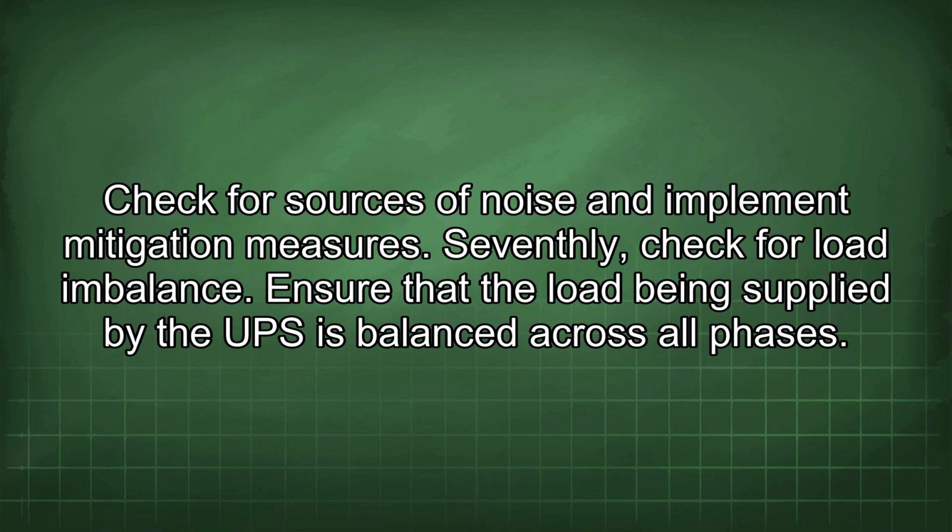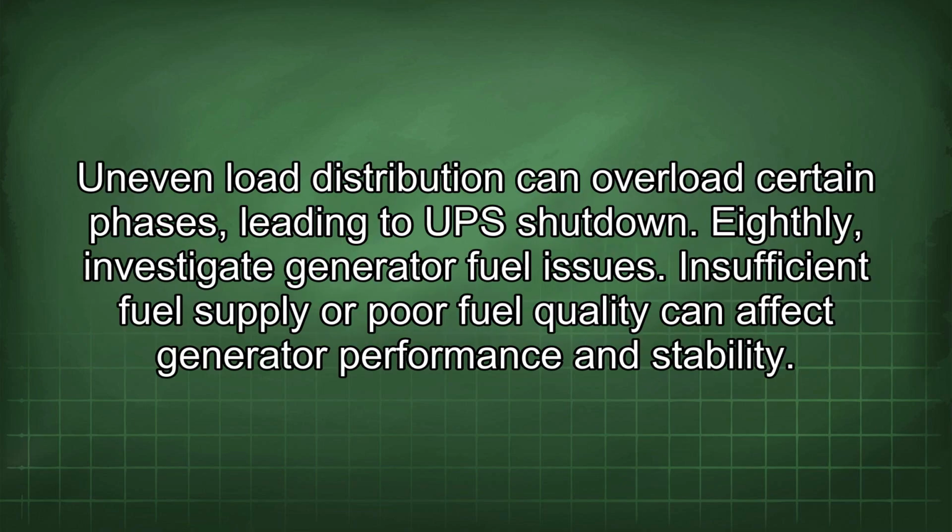Seventhly, check for load imbalance. Ensure that the load being supplied by the UPS is balanced across all phases. An uneven load distribution can overload certain phases, leading to UPS shutdown.